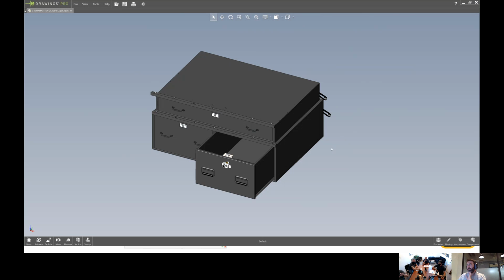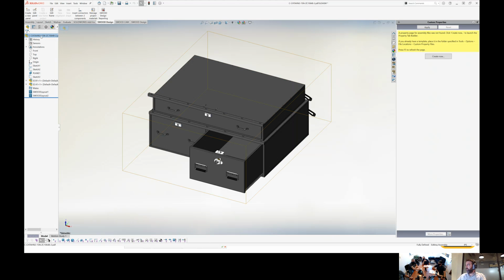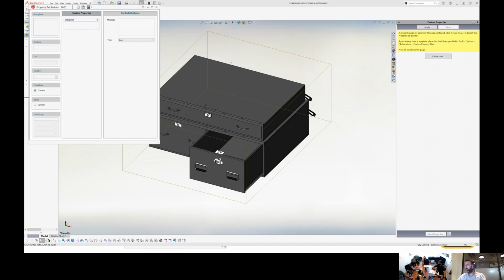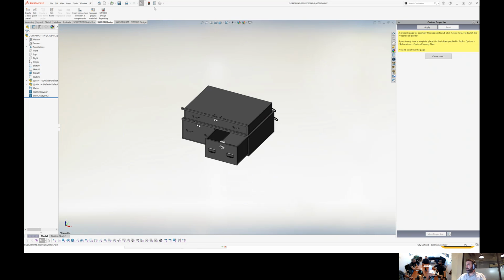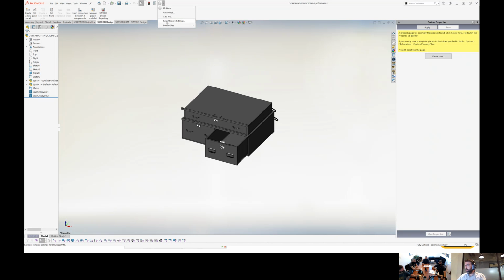My first question was, can we define more than one custom explosion? It sounds like there can be one that you create in SolidWorks, but you can do multiple, and they'll land here too. Each different explosion would be a different configuration. And explosions can even isolate and suppress parts, can they? Yes. Can we have a drawer explosion? Outer box. Yeah, that'd be cool. You just do the same thing. Because when you go into an explosion, you can set hide the parts. It's just like a view or configuration. Yeah, that's all it is.